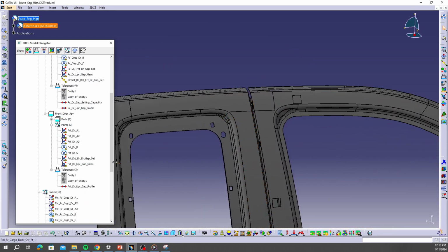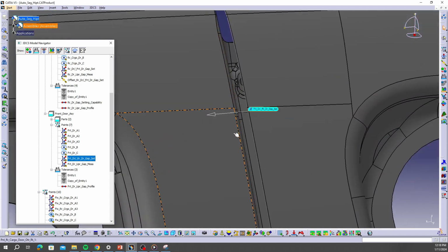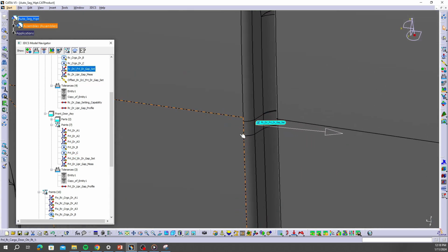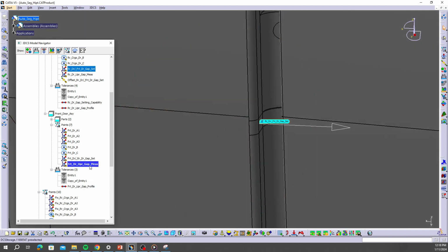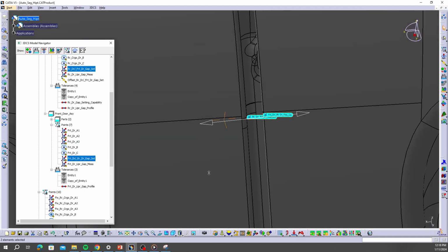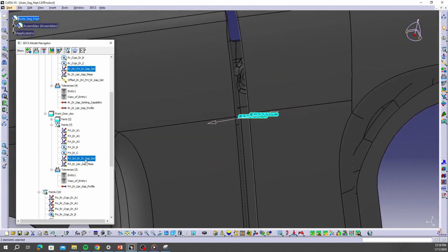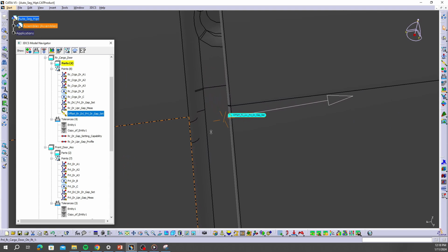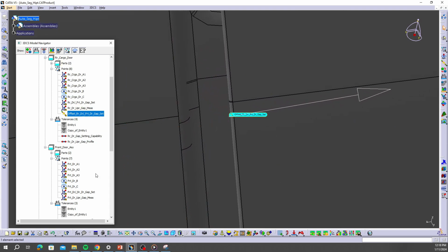So let's take a look here at this gap set point. Set here on the front door, and the rear door point is there on the rear door. Now there is a gap of about 6.3 millimeters, somewhere in that range. And I created an offset of one of the points, in this case the rear door. So I offset this gap set point, that nominal gap here, that distance, so that both of the points that I'm using in the move are on the same plane.